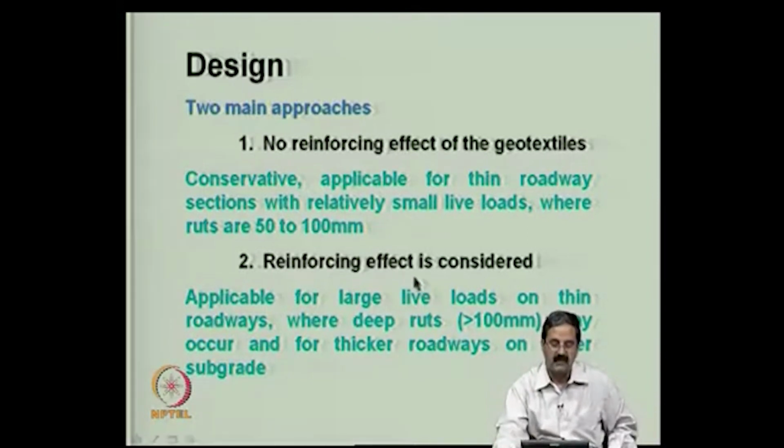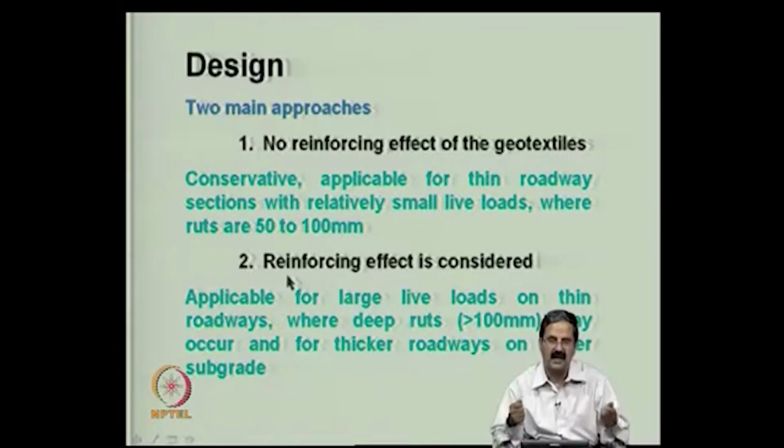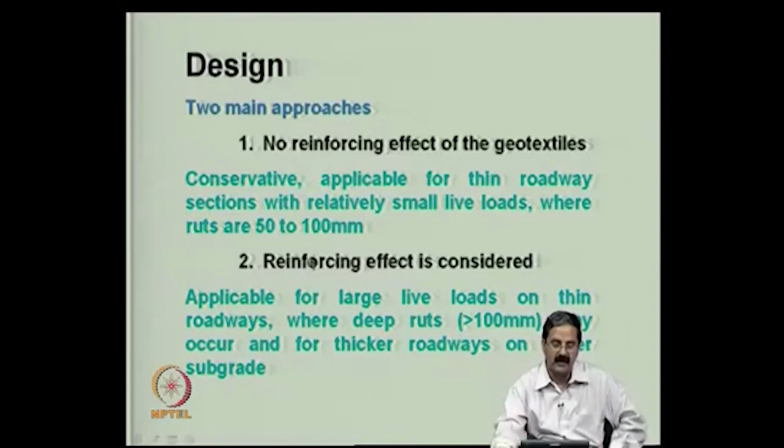So, that is one thing. The second thing is, if you put a somewhat stiffer material, like instead of I want a geogrid which is somewhat stronger, I will be able to take advantage of that, and then I can use it for live loads which are higher, and rut depths are also higher.